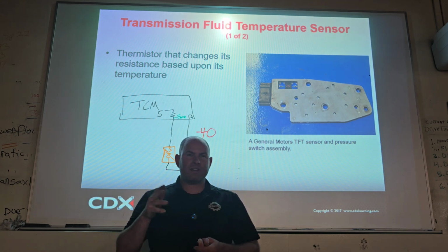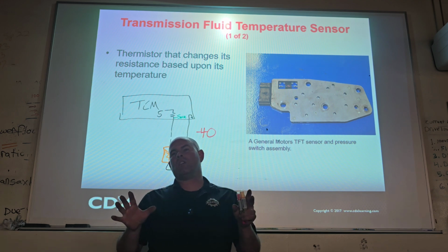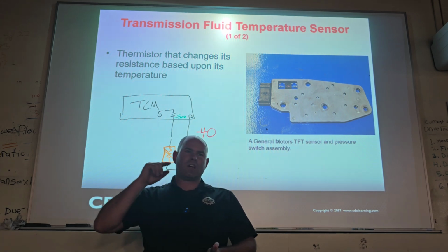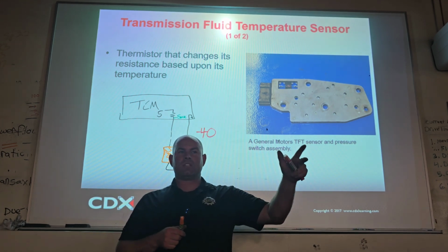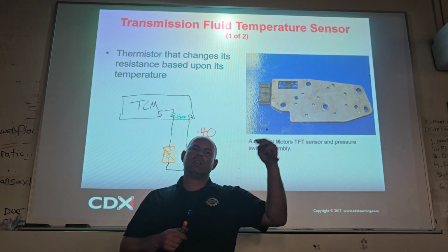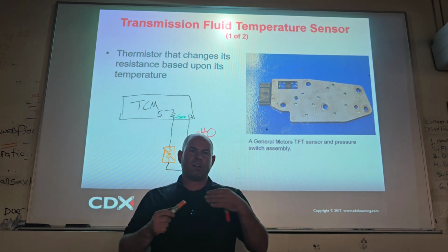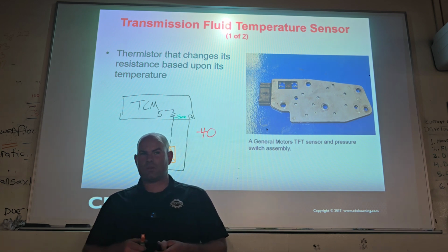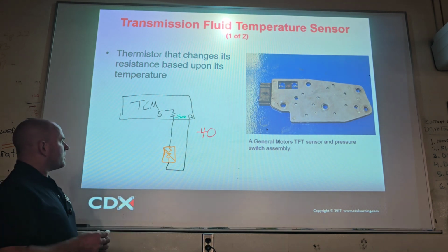Now, listening to that, don't you think you'd start with checking for codes? I didn't get any more involved than that, but I said the first thing you want to do is check for codes. You're probably going to be seeing something for vehicle speed sensor, and you need to check codes on all the modules. Because sometimes they might use a wheel speed sensor, send that to the ABS unit, then the ABS unit may send that on the CAN network to control the upshift, right? So you've got to really know how to do the diagnosis. You don't just say, oh, it's got a code, let me replace the transmission. Cool?